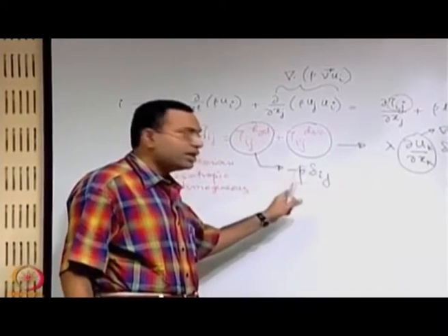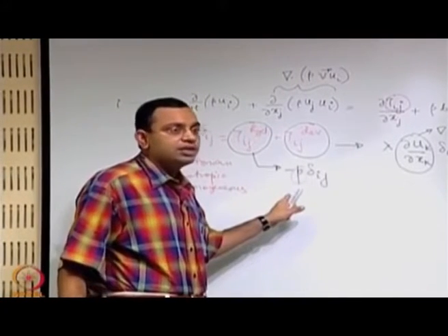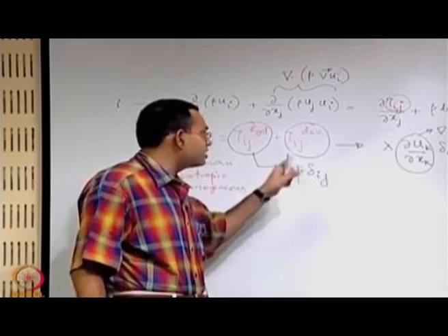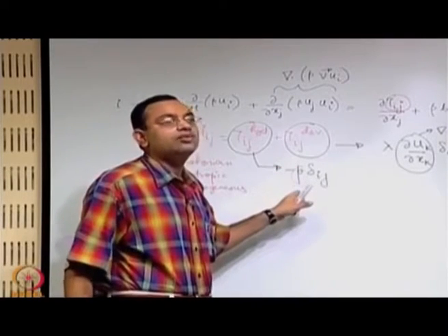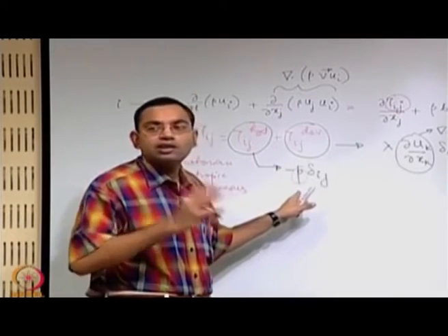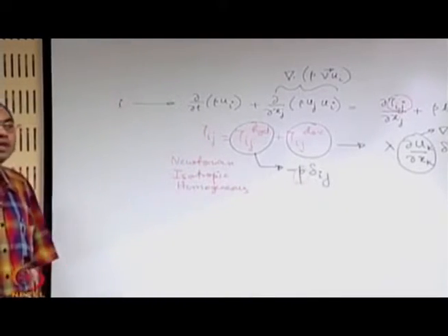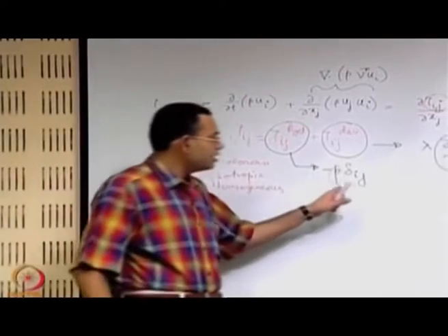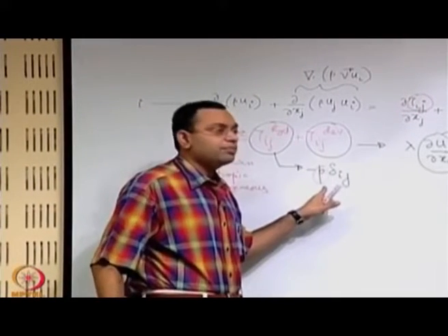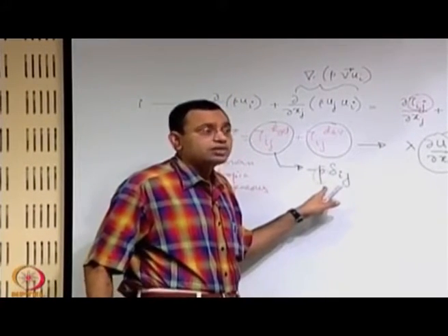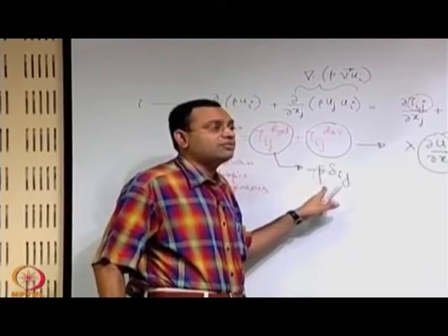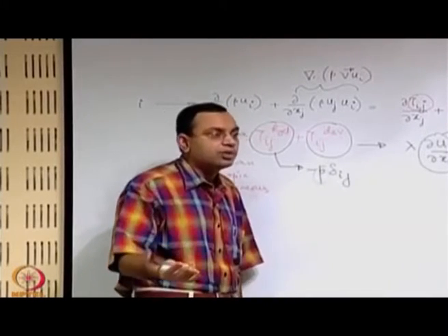So, thermodynamically what it means is that if you know at a point what is, say, density and temperature, you find out what is pressure by having a functional relationship with those. So, if you have two independent intensive thermodynamic properties, by that you are able to describe pressure as a thermodynamic property. So, it is a thermodynamic property because it is a function of two other independent thermodynamic properties.